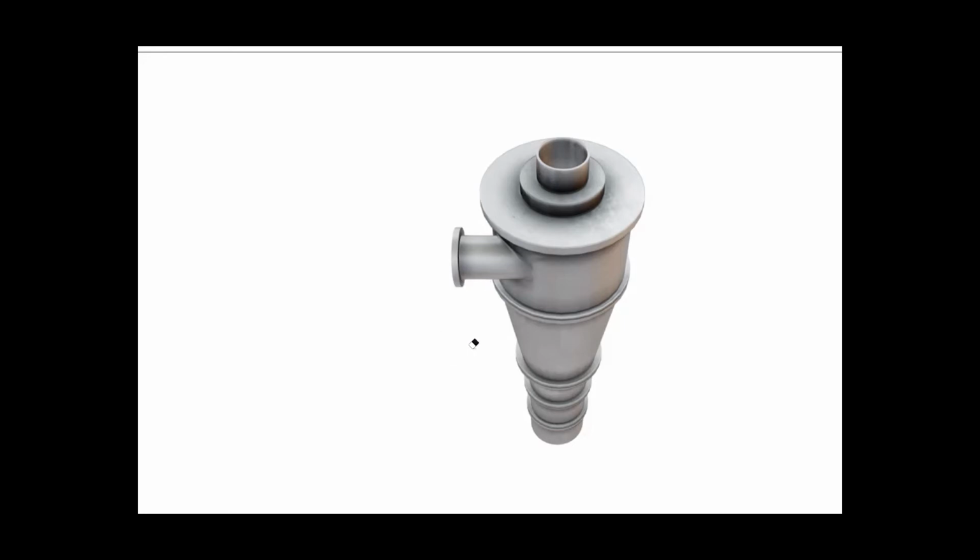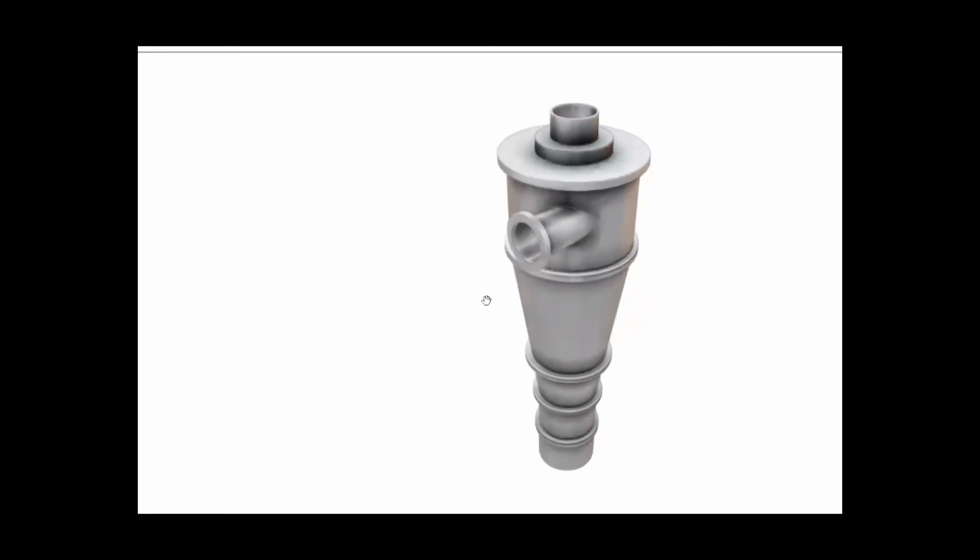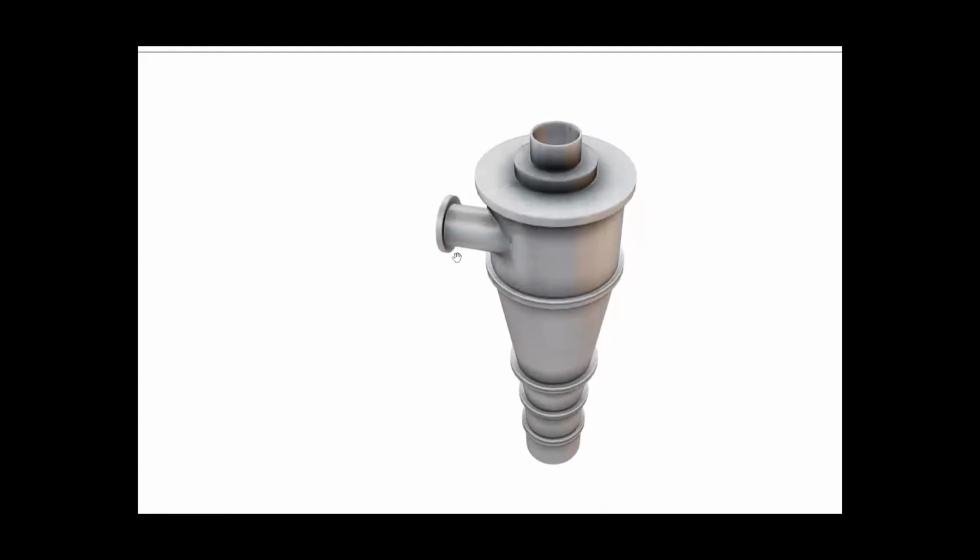The steam comes from here with very high velocity, carrying water droplets, and it moves with a tangential or linear velocity around the circle. When moving with this linear velocity, the water has more inertia than steam, so it hits the walls and moves around and around and goes to the bottom into the steam trap set.